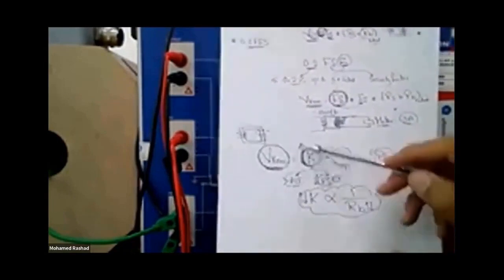This equation, engineer, if my test result for the RCT increases, it means it will affect the factor and make this factor low. Consequently, I might find that my test result could be incorrect due to a wrong connection regarding what? Regarding the measurement of the CT resistance, because this equation tells you this is only the CT resistance, the resistance of the CT winding. But when you made an incorrect connection, you measured the resistance of the windings plus the resistance of the wires, and thus the total resistance increased here.